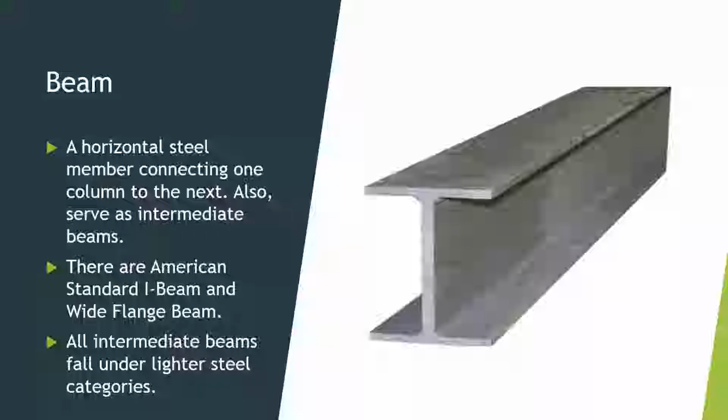The wide flange beam, which is another type of beam, can be used as a beam or a column depending on its application. You'll see that on the print written as an H, a B, a CB, and even a WF for wide flange, which makes sense to call it a WF. Now, this one has a nominal depth for designation. I want you guys to write this down on the sheet of paper there and we'll discuss it: 12-inch, capital W, capital F, which is WF for wide flange, and then 85.